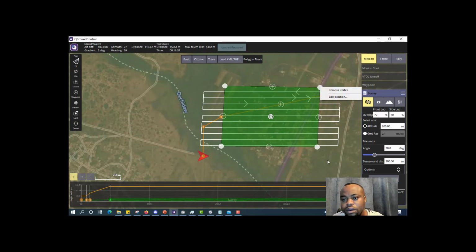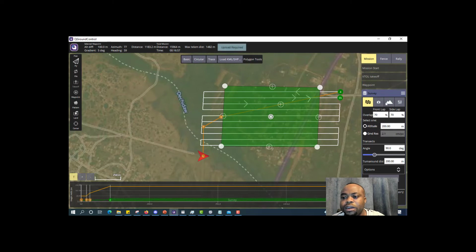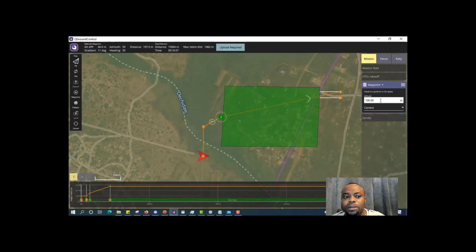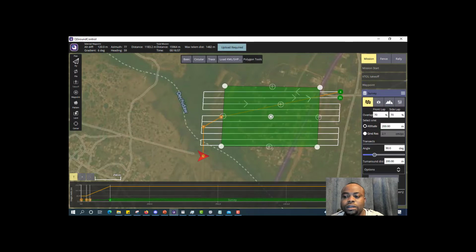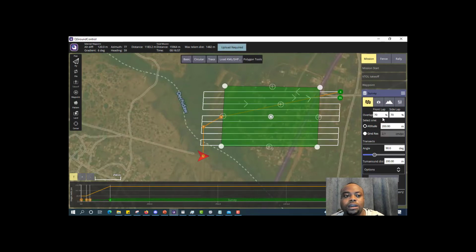Great. Now here I have my third waypoint that is going into the mission area. I'm flying at 200 meters. So let me find a way to reduce that height. Let me put somewhere around 90, or maybe 80. And then have a look. Okay, this is fairly good. So I build it from 60, 80, and then I enter my flight altitude, which is 200 meters.